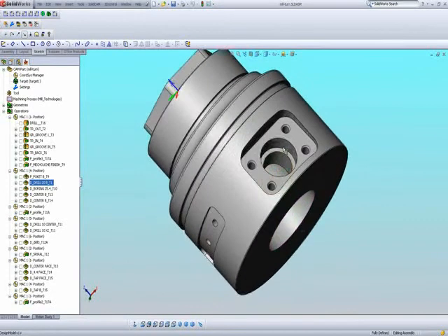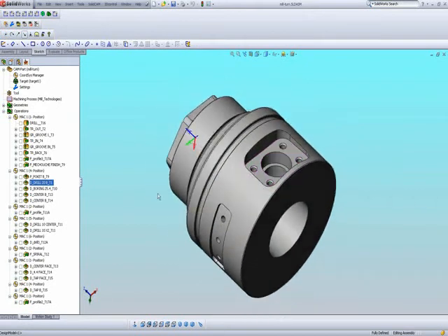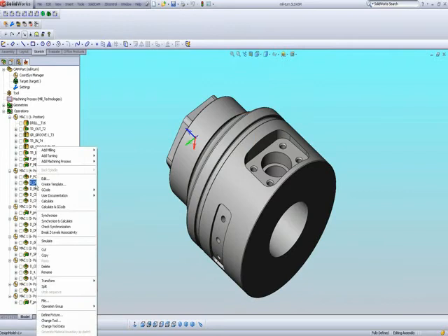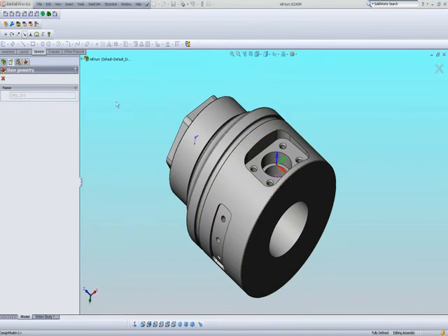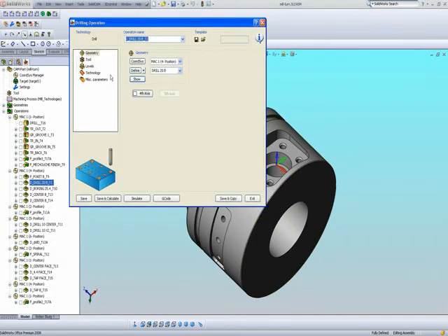Now, continuing in my Mac 1 position 4, I still have to drill out this hole inside over here and these 4 holes over here. So in this particular operation, as seen over here, I've gone through the middle, showing my geometry right in the middle of the part. I've used a simple drill of a 20mm drill.